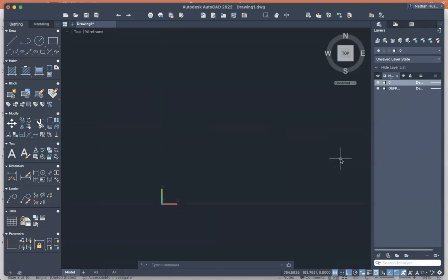Okay, so we know that when we are drawing in AutoCAD, we don't have any angles unless we specify we want a certain angle, right? So to specify that certain angle where we need it for our isometric drawing, what you need to do is type in Isodraft. Here you have several options. You have orthographic, which is what we currently use in our labs when we draw our front views, and isoplane left is in the isometric mode, isoplane top and isoplane right is in the isometric mode.